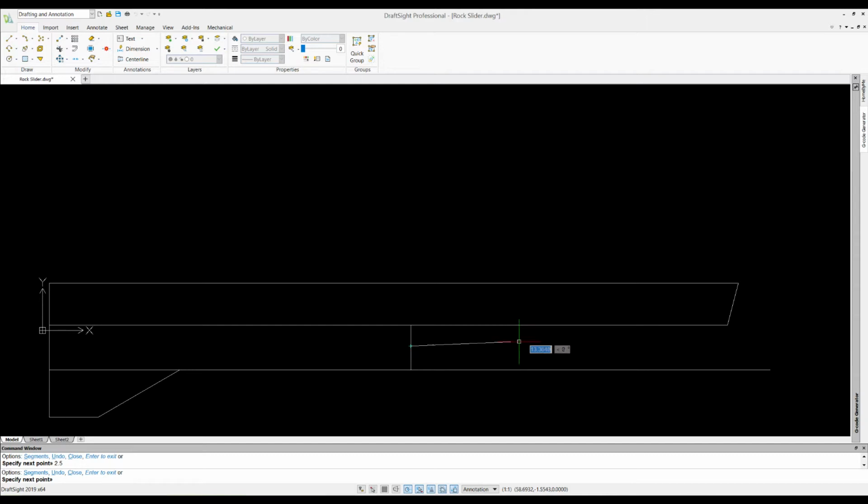So this is where, because this thing is perfectly accurate, you can just do the math and snap over. Since everything's perfectly accurate, there are no stack-up errors. So we're 44 and a half to 62 is where we needed it. So that is to there. Now this is where our upper control arm mount is, right in, well, right here, I should say. This is the transmission cross member right here, and right here is that upper control arm mount, and it would be hitting that line, so we actually need to give it some clearance.